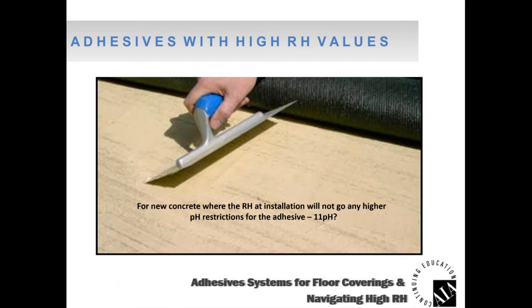So if that adhesive goes to 100 RH and the pH is only 11, well, if we get to 100 RH and we've got condensed liquid water and the pH goes to 12 and there's a failure, then that adhesive manufacturer is walking away because the pH was higher than their maximum. So it's critical for everybody to look at what that maximum pH value is of that adhesive for those reasons.